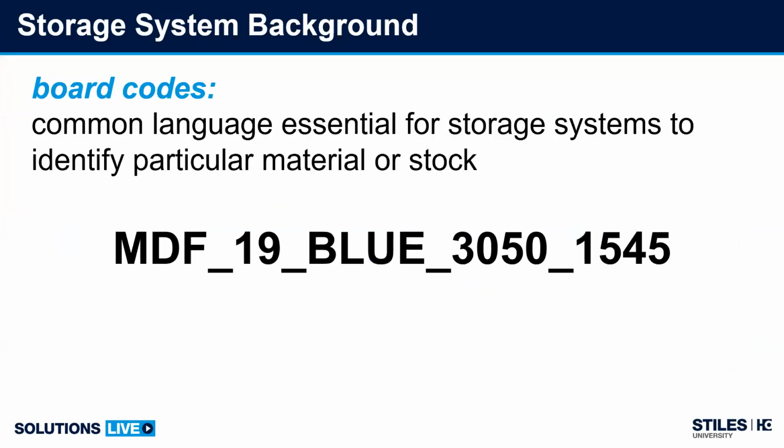One of the things that's vitally important within the system, and anybody who's been running the system knows this: if you are incorporating a saw and using CutRite, you've probably already created your board code list. We just bring that board code list up to the IntelliStore system or to the WoodStore system. But those board codes need to match. They have to be identically the same between the two softwares. Otherwise, we start having communication issues. We have inventory issues.